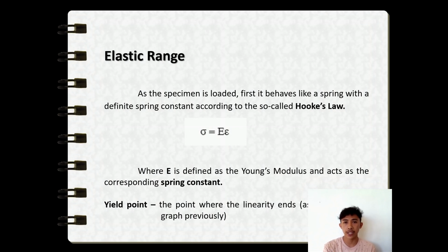The yield point is the material property defined as the stress at which a material begins to deform plastically. Prior to the yield point, the material will deform elastically and will return to its original shape when the applied stress is removed. Once the yield point is passed, some fraction of the deformation will be permanent and non-reversible. The yield point determines the limits of performance for mechanical components, since it represents the upper limit to the forces that can be applied without permanent deformation. The mechanical strength of the material corresponding to the yield point is defined as the yield strength.